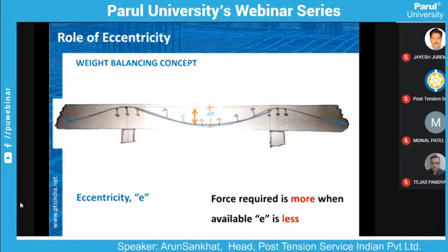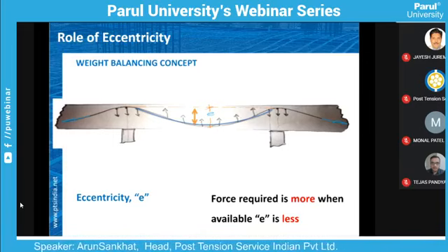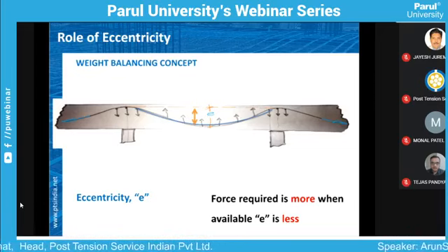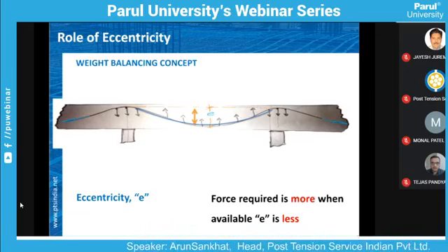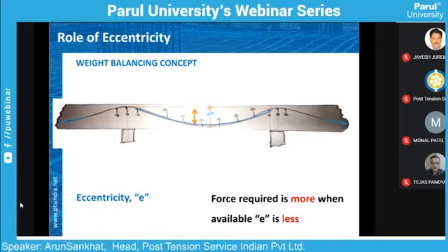The IS 456 code is there to make sure about the minimum criteria and all design requirements for RCC buildings. So if we refer to the span by D ratio given in the IS 456 code, for a continuous beam it is 26, for a simply supported beam it is 20, and again this is restricted up to 10-meter span.